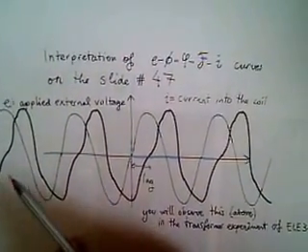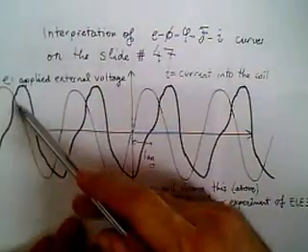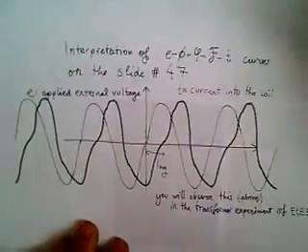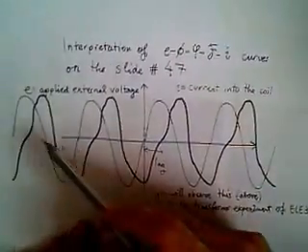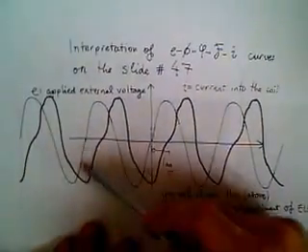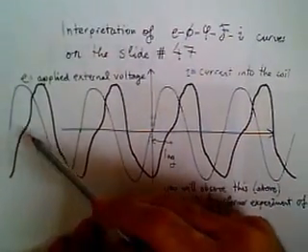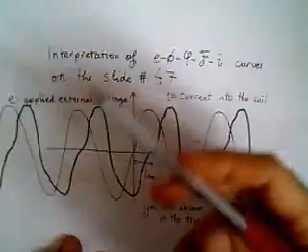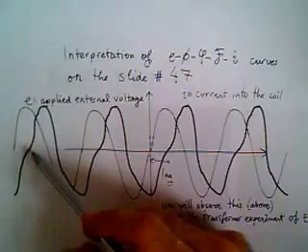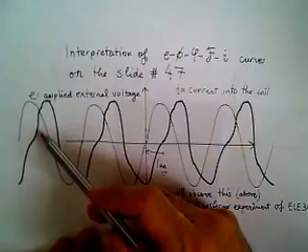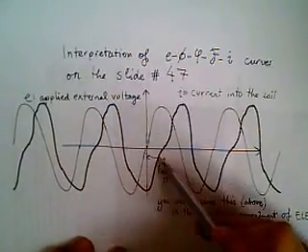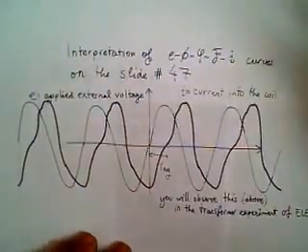In those systems, current or voltage at the terminals are assumed to be very good sinusoids. We assume the voltage is perfect and the current lags this voltage. This is usually the case in those systems, and this current, due to the nonlinear structure of the magnetic material, is not a perfect sinusoid. So it follows some kind of curve like this.